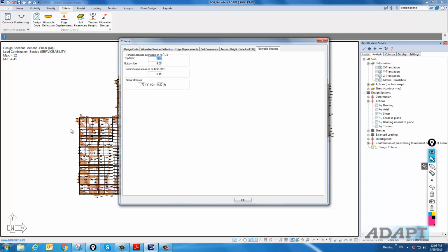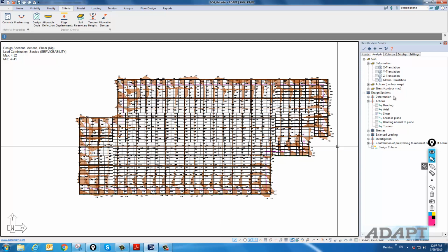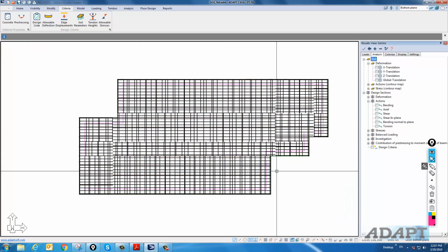because that exceeds my maximum shear stress using the minimum width of the strip. So that's a way to also check this kind of manually, but do it much quicker than checking each of the different design cuts. All right, so that's center lift.